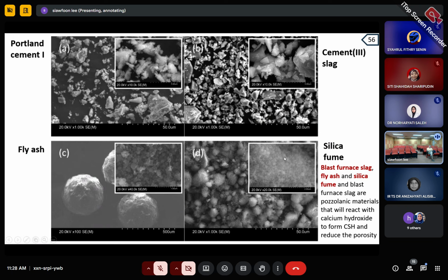And then of course, all these kinds of structures will influence the mechanical properties or the flowability of the concrete, because the concrete, before it gets hardened, needs to flow. For example, people study self-compacting concrete, and all these things they need to know very well. Of course, the addition of fly ash, slag and silica fume, they have another property. What is the property?